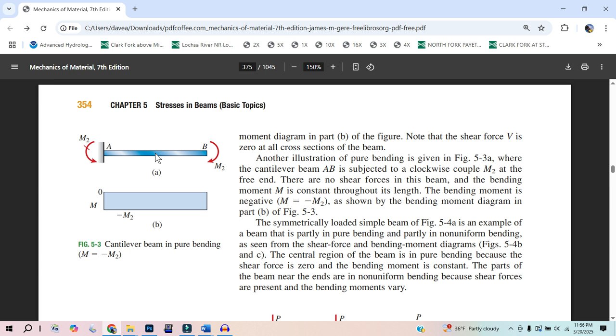So it's very good practice, even though this is just a constant line, to take a cut right here. Take a cut at halfway, 3/4, and then try to take a cut at the extremes, like almost full L, 0.99 L, and then do the opposite. Come over here and take a cut at 1/100th of the length. And what you'll see is that we have this little segment. We know the force on this side is going to be a moment that way. We have to match it with a moment this way. And again, this moment can be thought of as a downward and upward force separated by a distance.